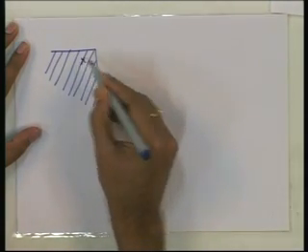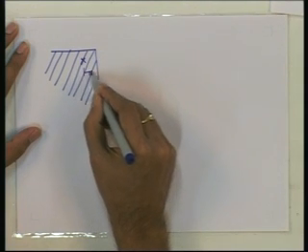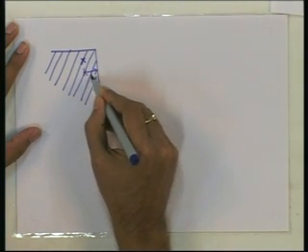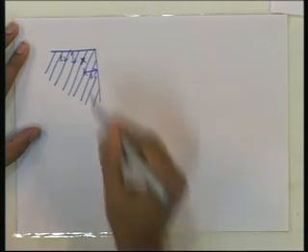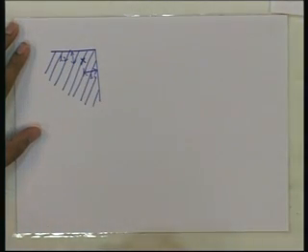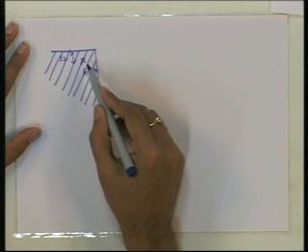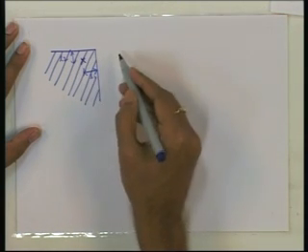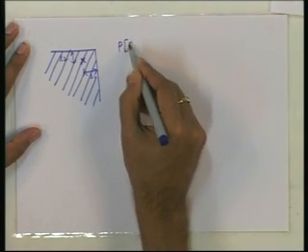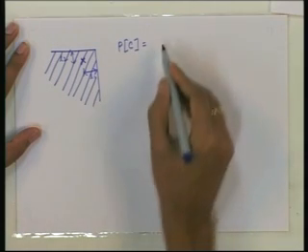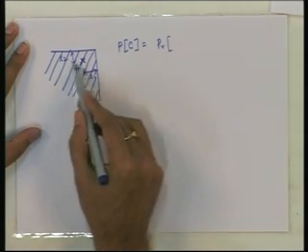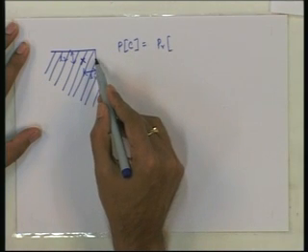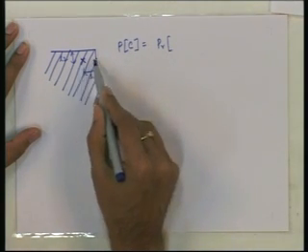So, this is our point, and suppose this distance is L1 and this distance is L2. Then what is the probability of correct decision for this point? Probability of correct decision for this point is the probability that N1, the noise component in this direction, is less than L1, then it will be on this side of the line.